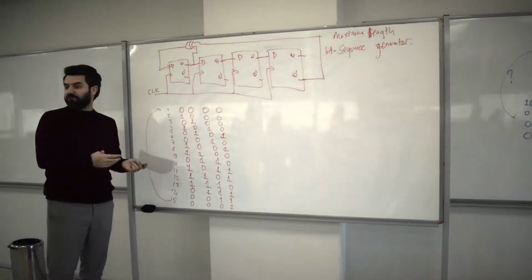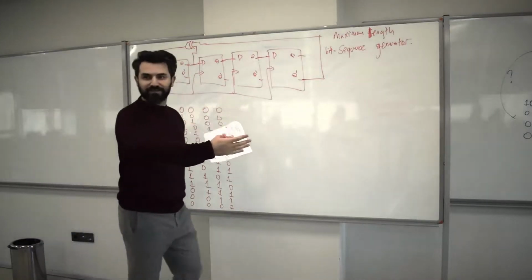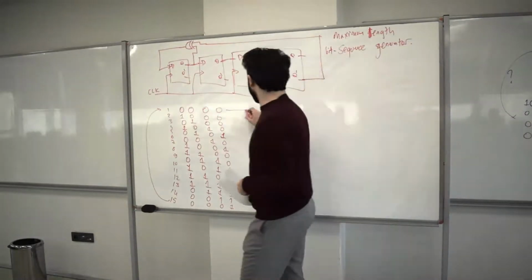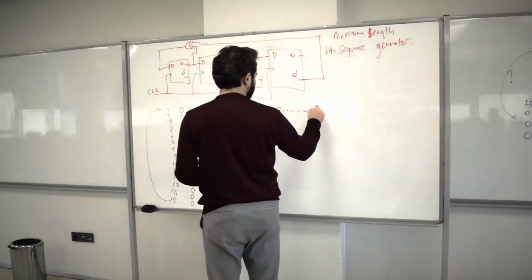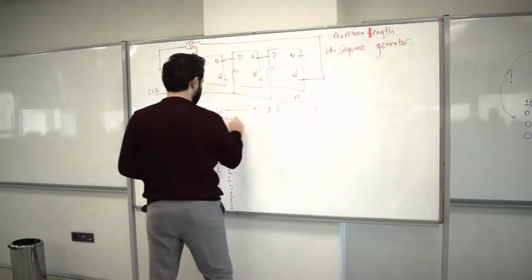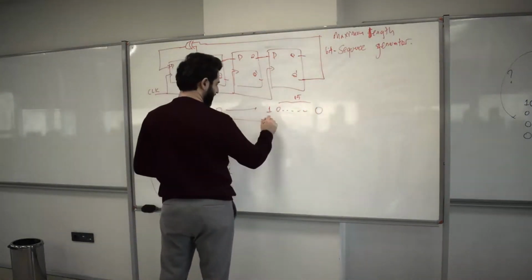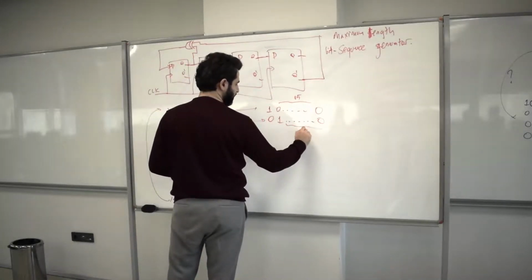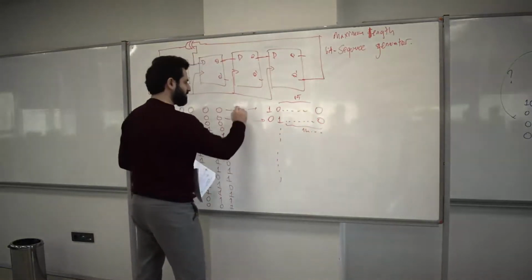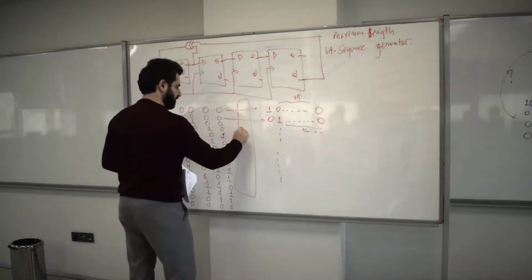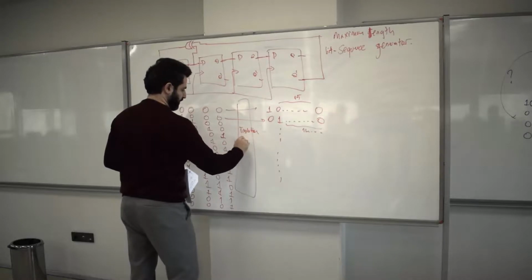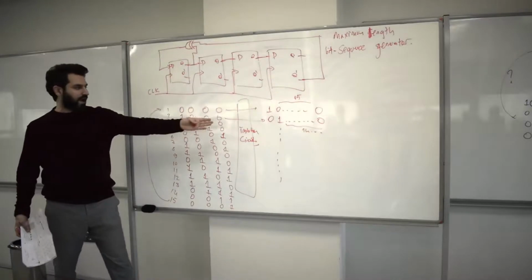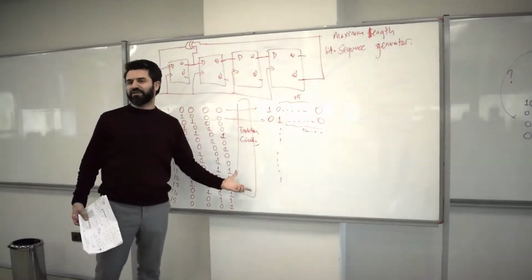Now, of course, you have to generate the format that we are familiar with, right? So that means this is going to go to 1 and 15 zeros. And then this is going to have to go to, let's say, 0, 1, and 0. So we got 14 zeros here, etc. So that means you have to have a translator here. Translation circuit. Not very hard. Again, there is no don't care here, so probably you have more combinational logic here, right?